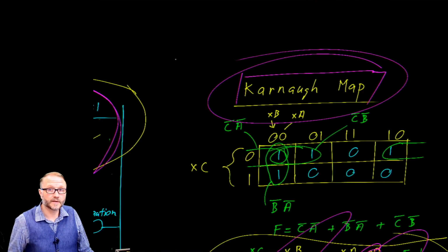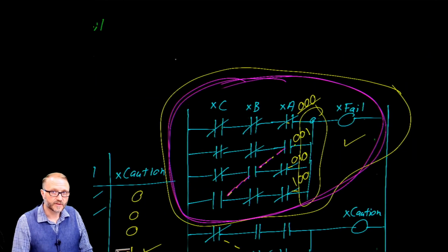Anyway, the Karnaugh map exists. It certainly can be used. There was a time when it would make sense to do this. For example, if you were using all of those ice cube relays, this would allow you to save relays. You could make your panels smaller. You could make them use less electricity. But that is gone. With a modern PLC, it's just not necessary. Don't be clever. Work for consistency and work for clarity.